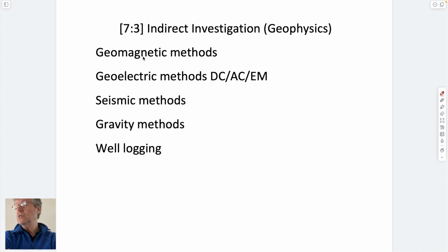And in soils, we talked about using split spoon and Shelby tube samplers. Split spoon for sands and gravels that are banged into the ground, Shelby tubes for fine-grained, cohesive materials, clays and silts, which are pushed into the ground and allow you to retrieve samples to take back to the office. And we closed out talking about direct push methods as well, to use as an analog.